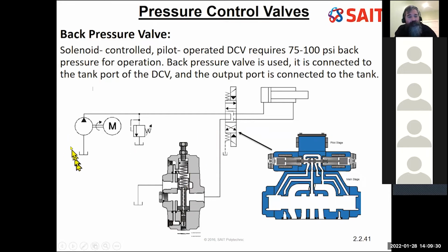What's important here is that at this stage, the fluid flows through from the center position into the valve. A bit of back pressure will build up, forcing this valve to open, allowing the fluid to pass through. It doesn't really just act on the surface. The surface on the top of the spool, or the inside of the spool, is the same as the surface here. I've got balanced forces acting on the spool, so it isn't going to move. But I do have this little channel going up under this little piston, so I've got this little extra surface area. So bigger surface area here plus here causes the valve to open, allowing the fluid to go through.